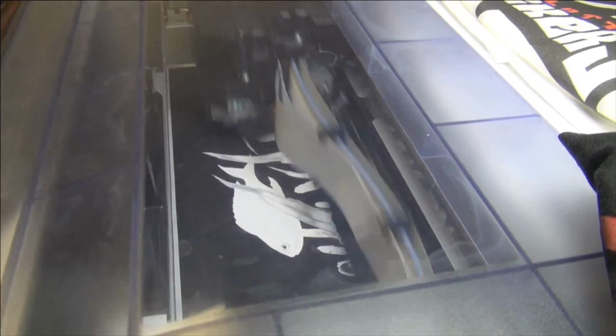So what happens on the dark shirts is it has to lay down a significant amount of white ink to lay the color on top of it, because the ink that is in here, if we did not pre-treat or lay down white ink, the CMYK ink is just going to essentially show through the shirt. You'll have a lot of strike through and you won't really be able to make out your design. So you're seeing right now worst case scenario for cost on a t-shirt.